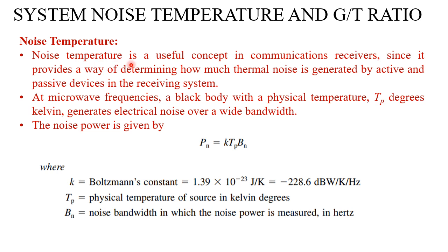Noise temperature is a useful concept in communication receivers since it provides a way of determining how much thermal noise is generated by active and passive devices in the receiving system. It is not exactly the actual temperature. This is equivalent noise temperature, mind it.